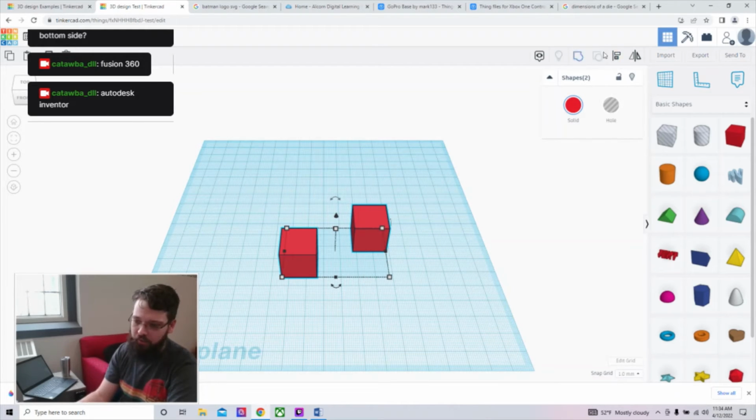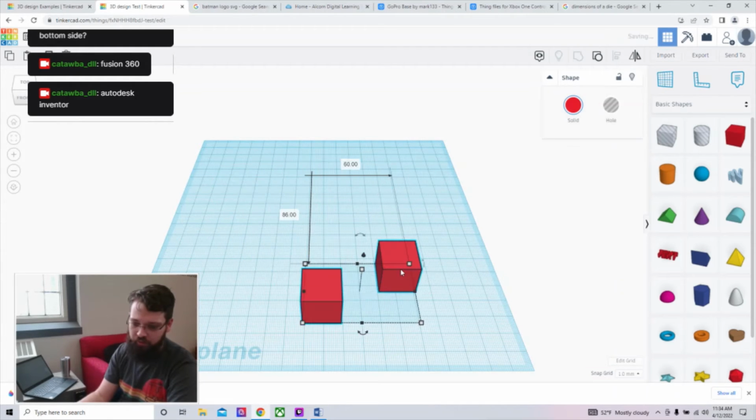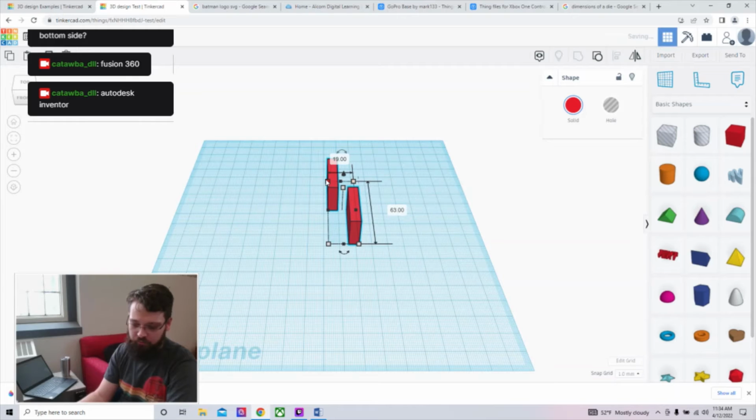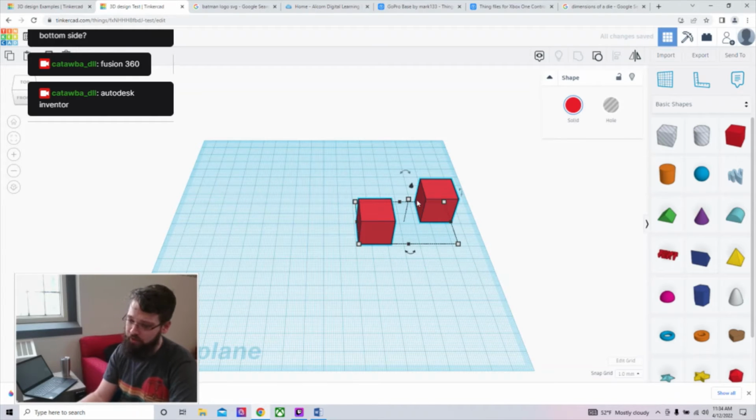In the upper right hand corner of the screen, you'll see what looks like a square and a circle combined into one shape. That's called group. If I hit that, it's also Control G. It groups those 2 things. So now once I move it, it will always move together. It will always reshape together.